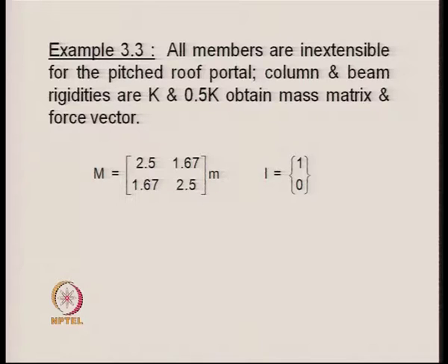On the right hand side of the equation, we have the mass times the ground acceleration. The second form of the equation was in terms of the total displacement of the structure, in which the second order differential equation had the total motion as the unknown. On the right hand side, we had the stiffness multiplied by the ground displacement plus the damping coefficient multiplied by the ground velocity.